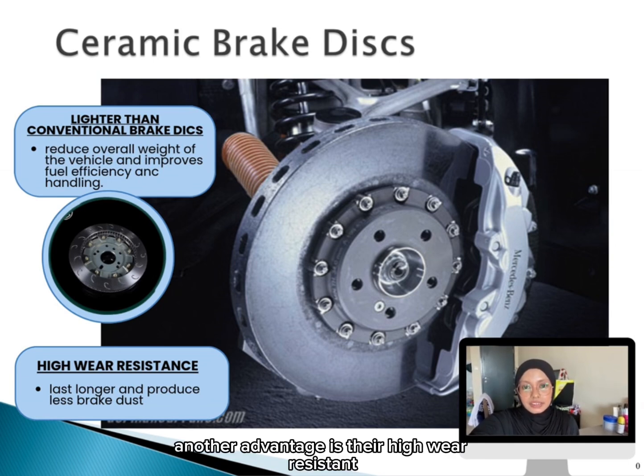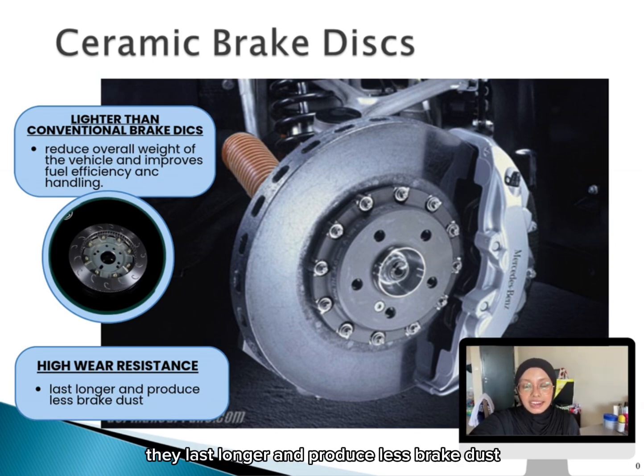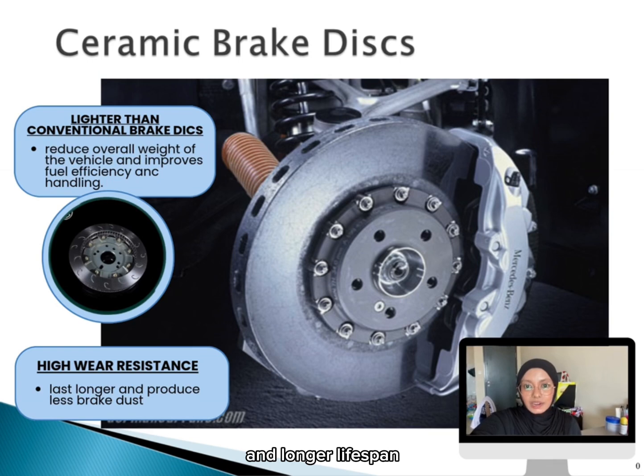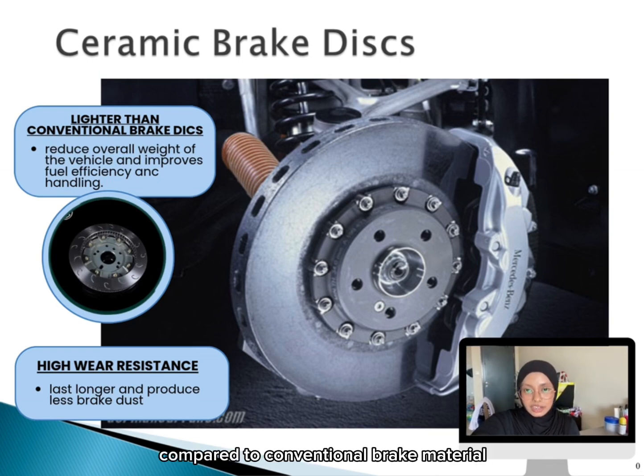Another advantage is their high wear resistance. They last longer and produce less brake dust. Therefore, ceramic brake discs provide better braking performance, improved thermal stability, and longer lifespan compared to conventional brake material.